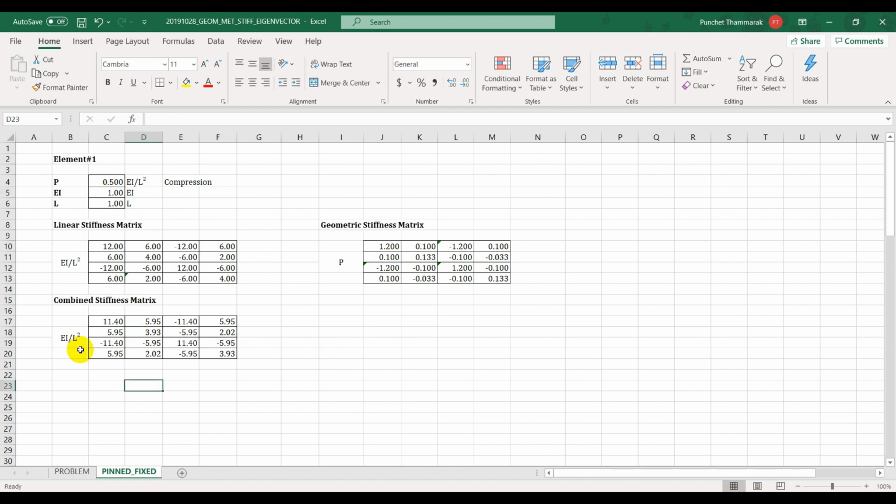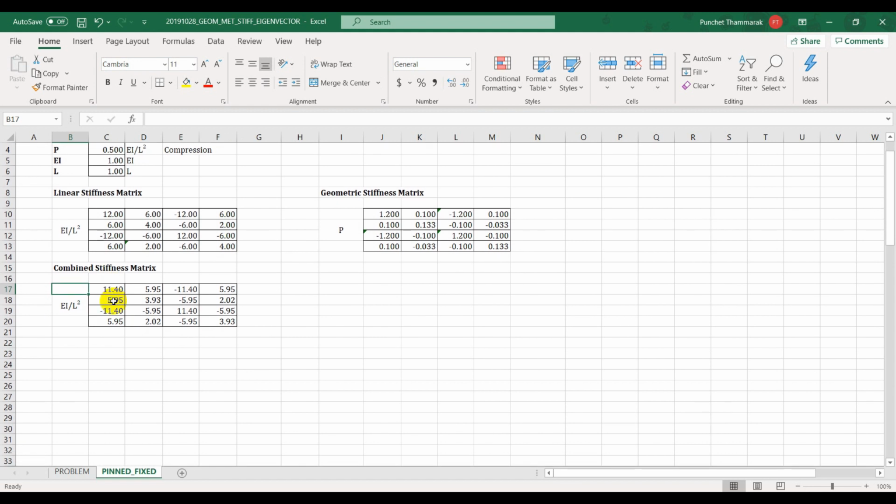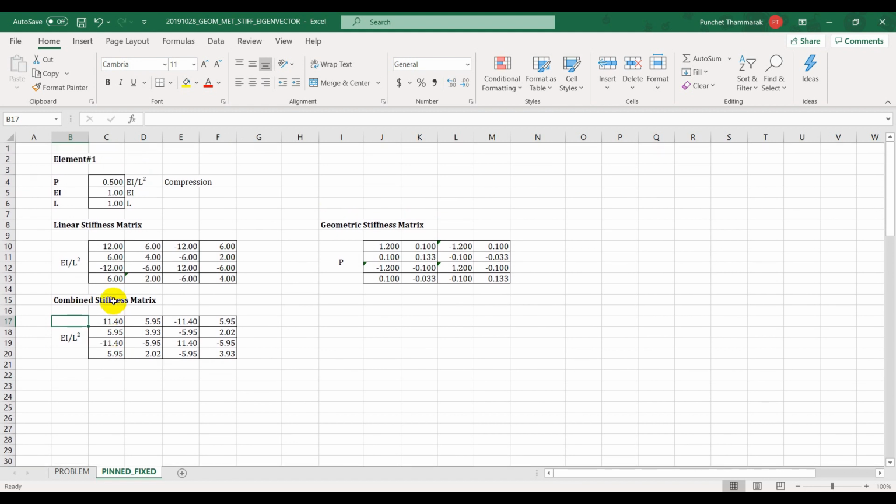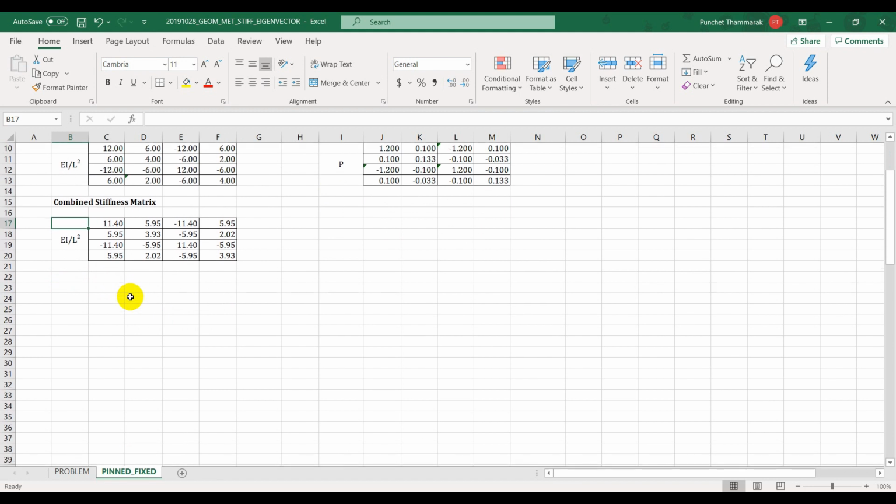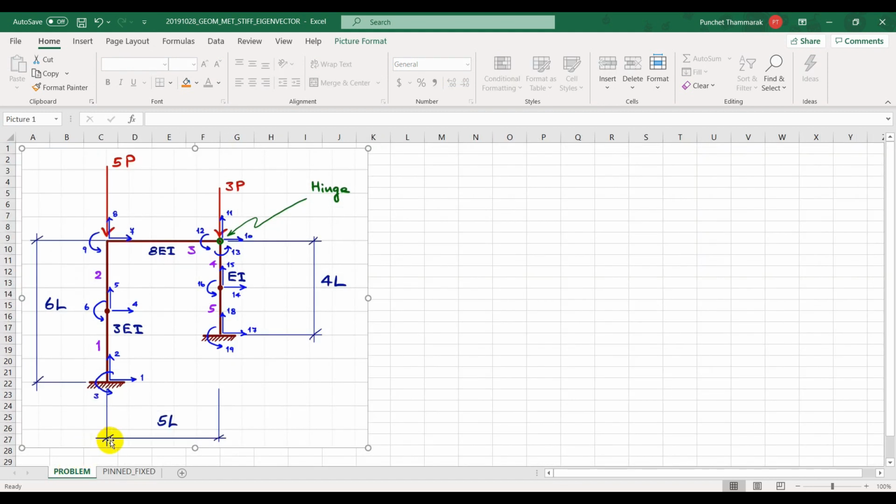All right, but over here, this is the local stiffness matrix of that individual element. So in order to make it easy for us to plug in and combine the stiffnesses from many elements, we will prepare the space which is the matrix, the K system for the whole problem, and this contains degrees of freedom from 1 to 19.